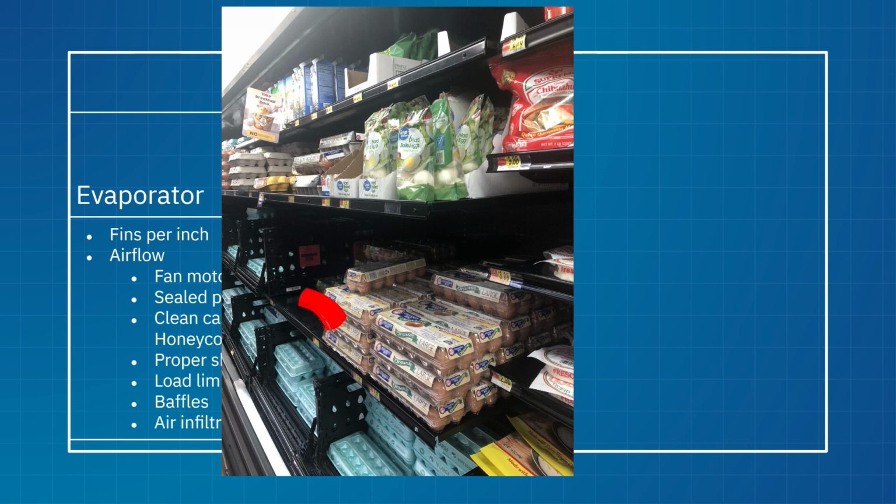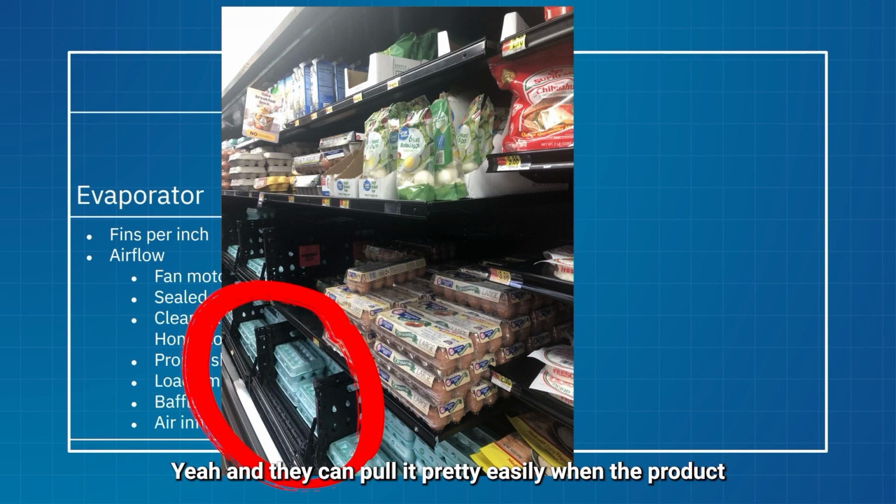So check this out too. This is a merchandiser that's not approved by the case manufacturer. It's a container that my associates can stock, set in the case, open, and walk away. They can pull it out pretty easily when they come back to it. Except for this front piece they unload, they pop down. That's my air return, guys. Is that okay? No.